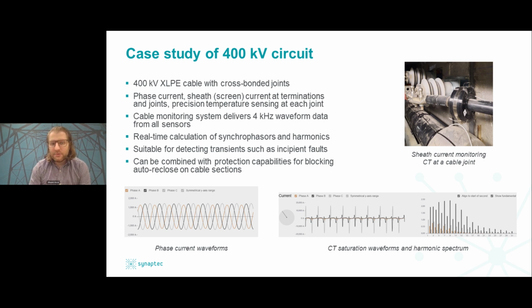So what we've done here is we're monitoring screen currents or sheath currents at multiple joints along the length of the cable, and also at the termination of the cable where it converts from overhead line into a cable. And we're also monitoring temperature at point locations along the length of the cable. So that gives us quite an interesting picture of everything that's going on with that cable at discrete locations where it's really important to measure it.